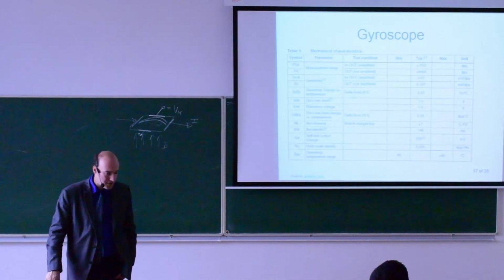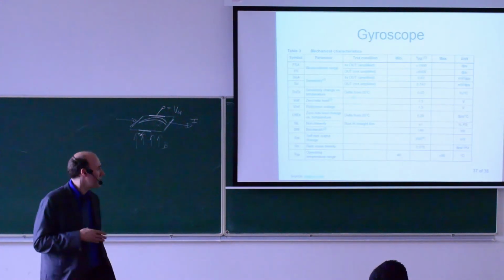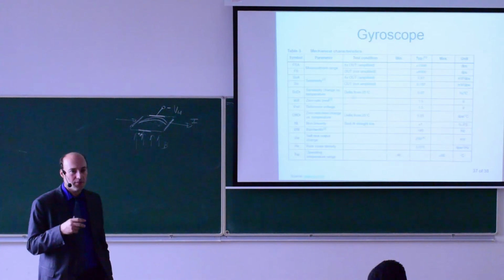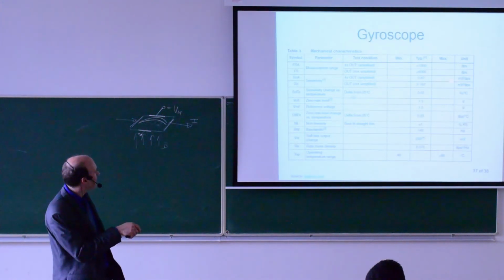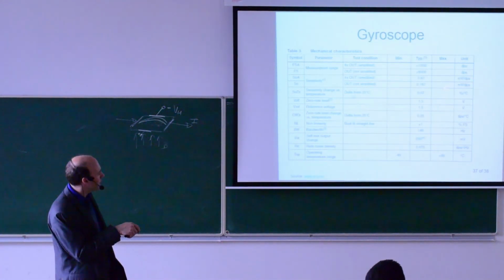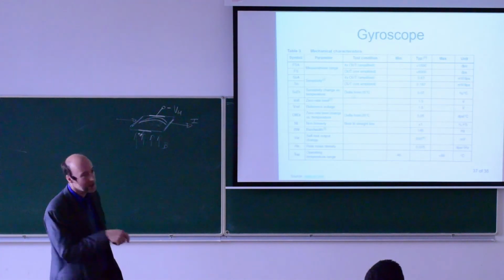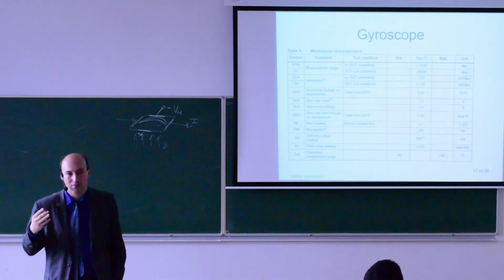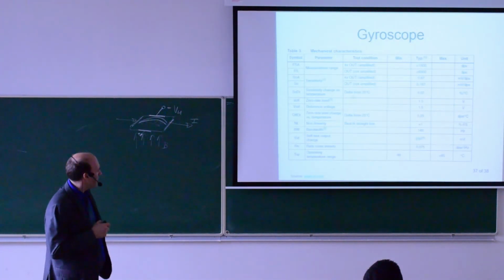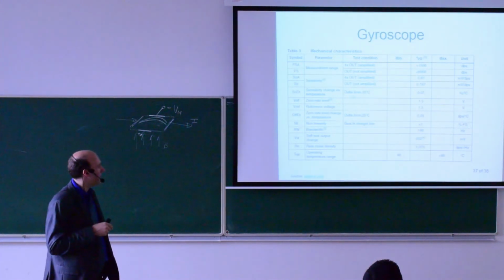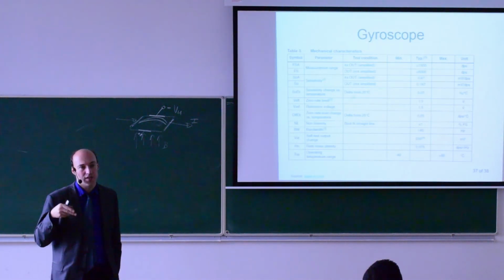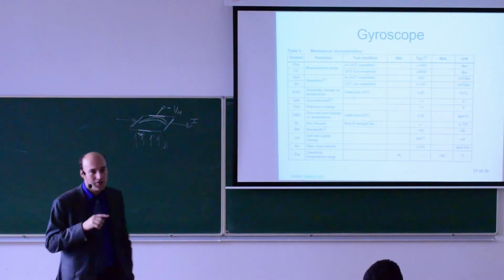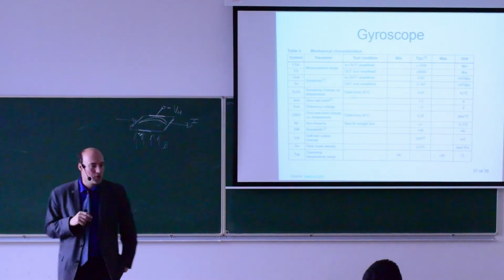In the data sheet of the gyroscope, the most important information is the output signal as a function of the input. So again, sensitivity. Typically something like this. This is a sensor with a voltage output, and you see millivolts per dps, degrees per second. So how many millivolts you will have if the speed is big. You can see also the measurement range, 1500 degrees per second. That's roughly 5 revolutions per second. This gives you roughly an idea in what applications this could be used.